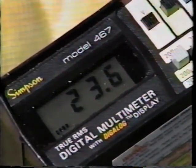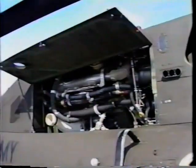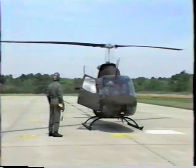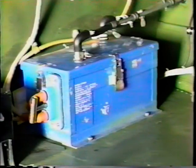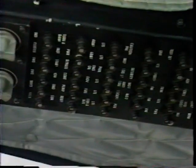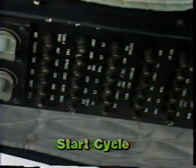To do this, you would use the combination type starter generator, located on the underside of the engine to the right of the aircraft's center line. In addition to starting the engine, the starter generator is used to charge the battery and supply power to all DC electrical components. To start this cycle, begin at the overhead console essential bus and find the igniter circuit breaker.